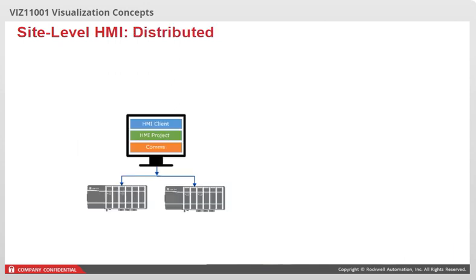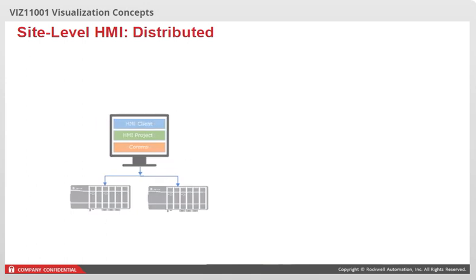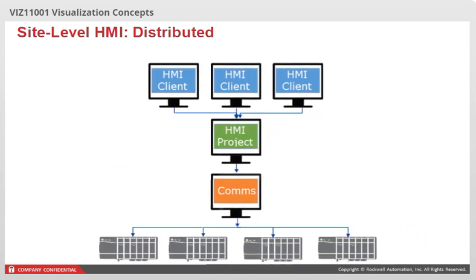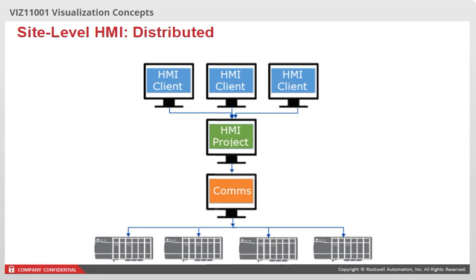As mentioned earlier, most HMI system vendors, including Rockwell Automation, choose to separate the software components based on their function. This multiple computer server-client architecture is referred to as a distributed HMI and is highly flexible. Running the components on multiple computers enables optimal scalability up to the customer's current and future needs, while the overall system is managed as a single application.